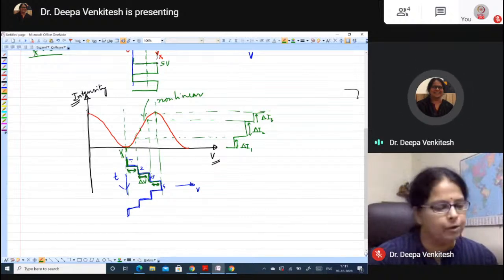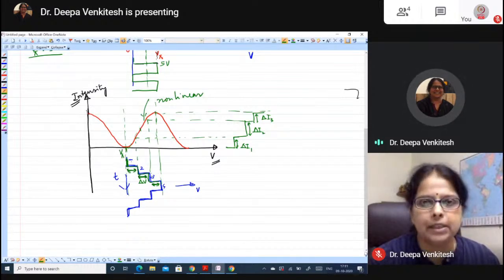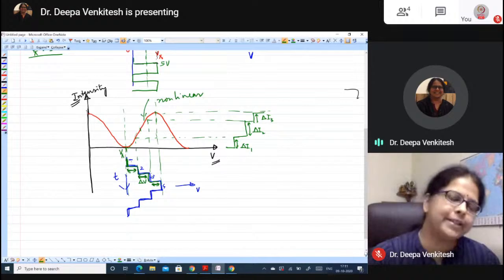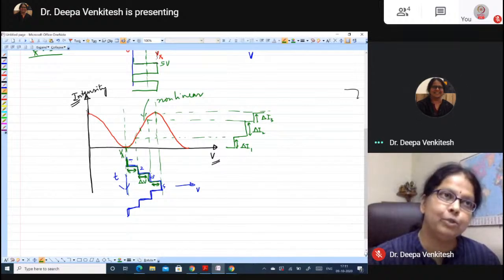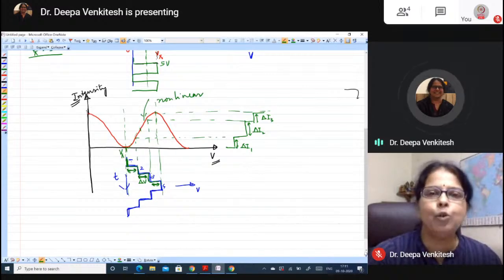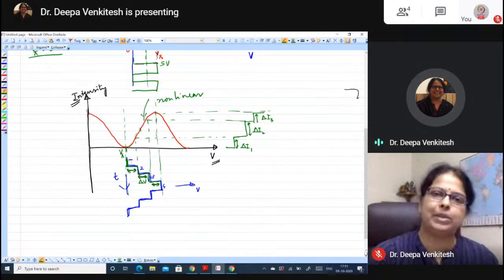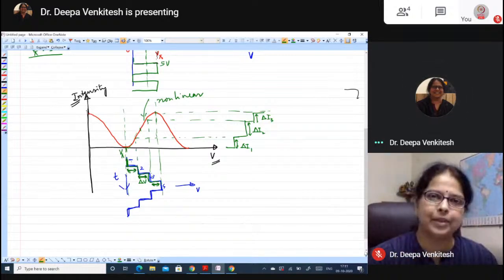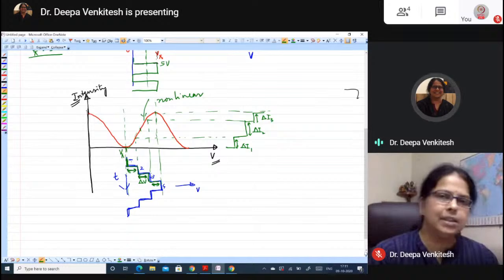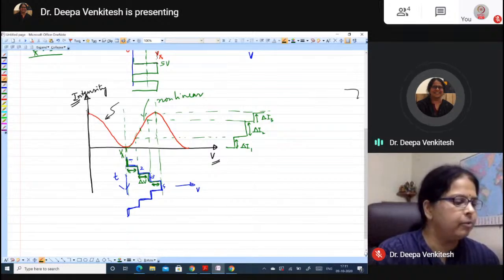So the slight subtlety here is that even though in PAM4 you can give 4 levels at the input and you get 4 output intensity levels, if you do not do a pre-compensation, the optical intensity levels are going to be unequally spaced. And that's not something you want in a communication system. You want the levels to be equally spaced. So how do you do that? The answer is very simple. You know this transfer curve, you know the form for this transfer curve.